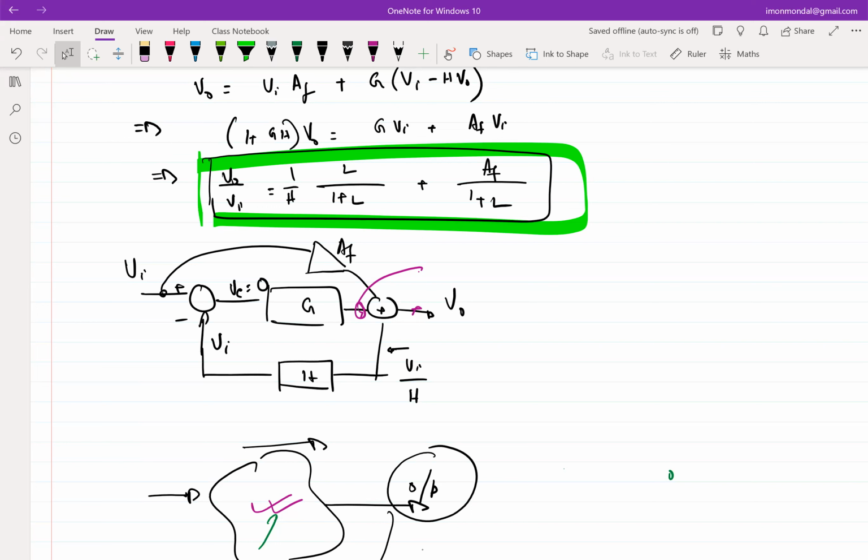So the path that is largely not getting affected by the loop gain if the loop gain is low, this path is the expected action. This is the expected loop. The expected loop should work properly because that is what we are designing for. But when you design for something, it need not be the only path that exists. There can be some extraneous paths. So what happens to those? We need a framework to analyze. So that essentially is the H naught. It is modeled as H naught. It's not as if we need that, but we cannot do away with it either.